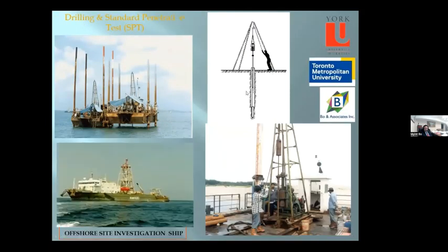This is a standard penetration test and the ground investigation carried out in a foreshore area using a jack-up pontoon. Some ground investigation is carried out in the offshore area using site investigation ships. This is an SPT hammer dropping to carry out the SPT test.